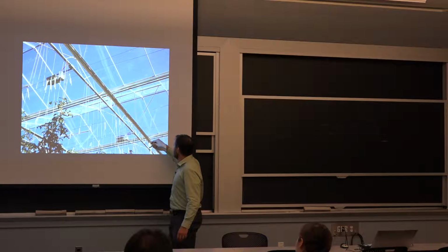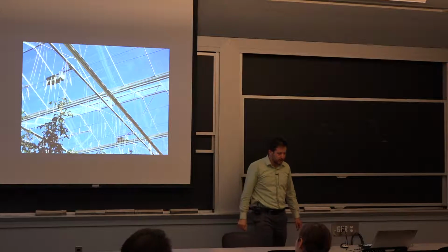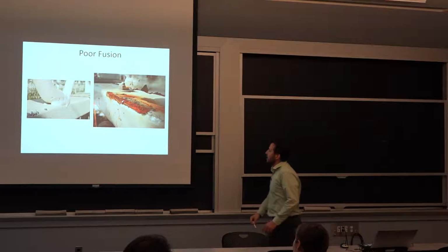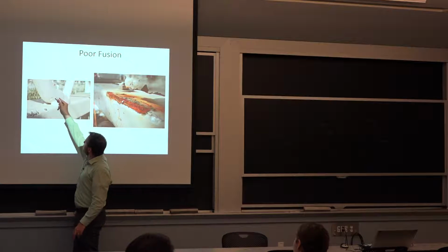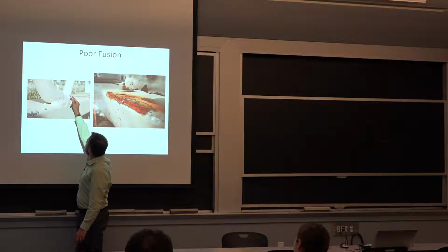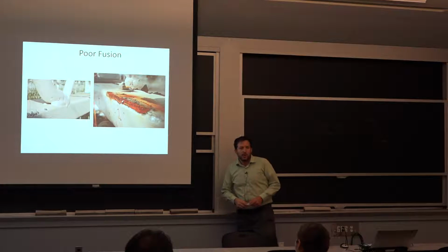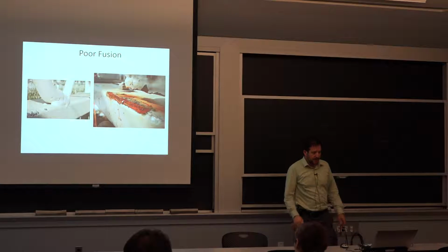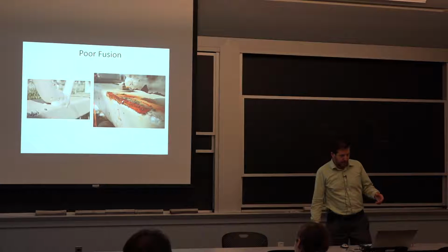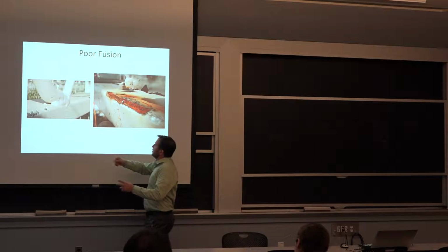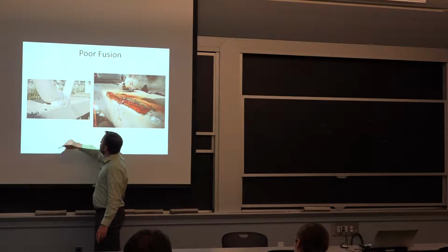Well, you see better the diagonals going up and down. Those are essentially transferring the shear load between the two chords, and you can see them in detail here. So we have a diagonal coming down, we have a little weld here, and then we have another diagonal going up. Just for weight and cost optimization, they had the diagonal in compression bigger than the one in tension. So we can already tell that the smaller one here is the one in tension.